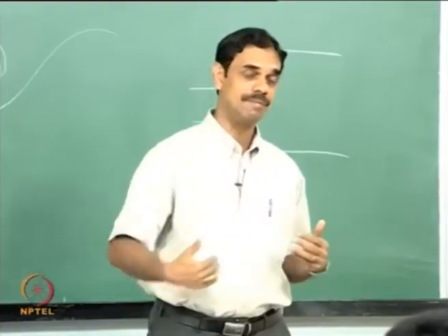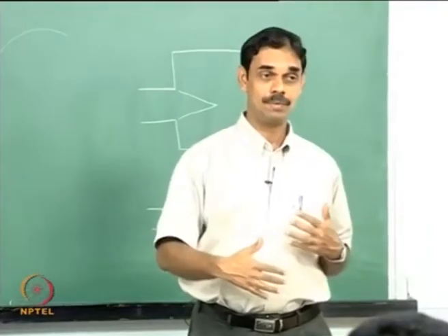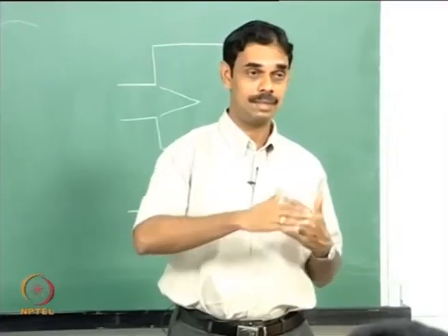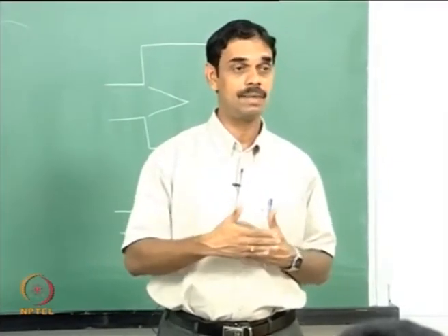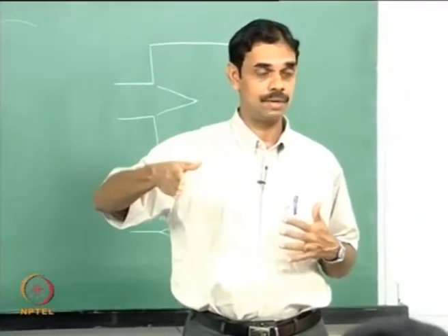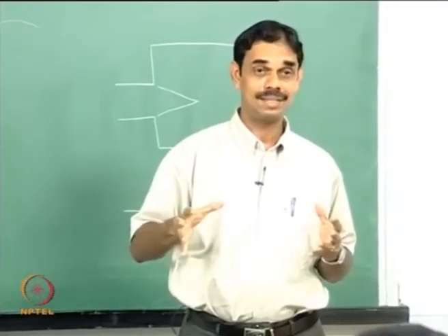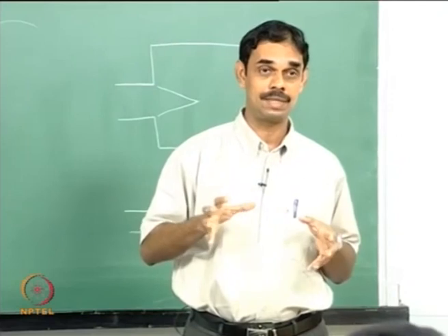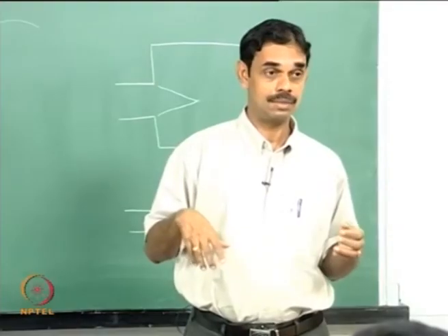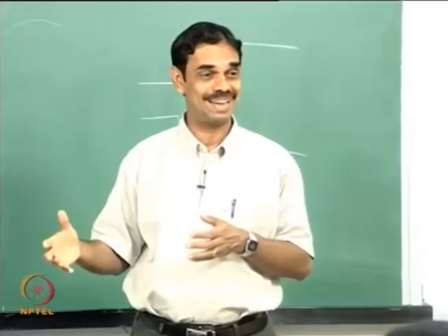But we are also greedy, we want to pump in a lot of mass flow rate, so we want a high velocity stream coming in. The moment there is a low velocity stream and a high velocity stream, the mixing layer or shear layer between them will be unstable and have this Kelvin-Helmholtz instability and roll up and so on. So we are not having the bluff body to shed vortices, we are having it there to hold the flame, to have a low velocity region where radicals are available which will ignite the coming mixture. But you can't have this and not have that.